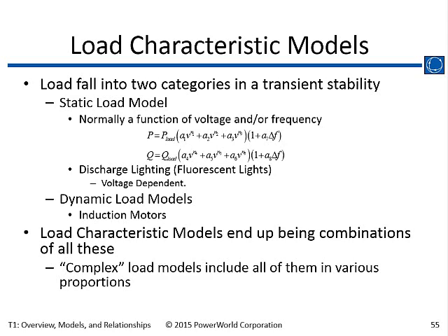Should we as an industry support the models necessary to do AGC? Because when you get into AGC, you have to say, following this disturbance, for example the double Palo Verde, how will the generators respond to get back to 60 hertz? So you have to model the ACE, and you have to know how the cost characteristics on the generators are going to come into play. That's something we as an industry haven't done. Could we do it? Yeah, we could. And PowerWorld does do it for some places.